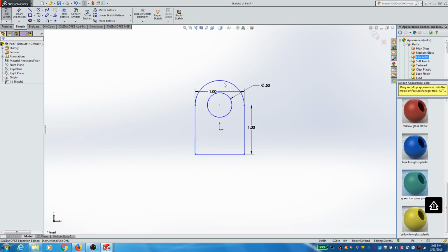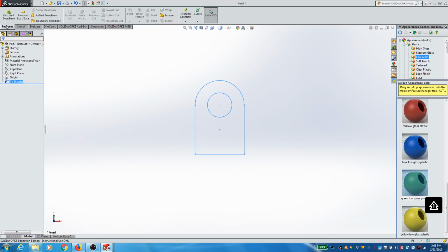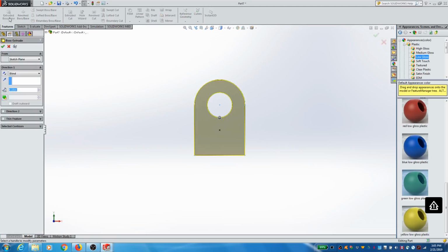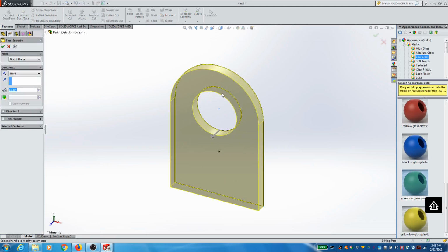Okay. So I've got the outer edges here of my tombstone, and I'm ready to actually now extrude. So I exited my sketch. I'm going to click on Extrude. And you can see that, again, it's smart. It says, hey, you drew this, what I think is an object here. I think that was a hole that you had, and this is going to be the solid piece. And I think you want to pull it forward. How far do you want to pull it forward?